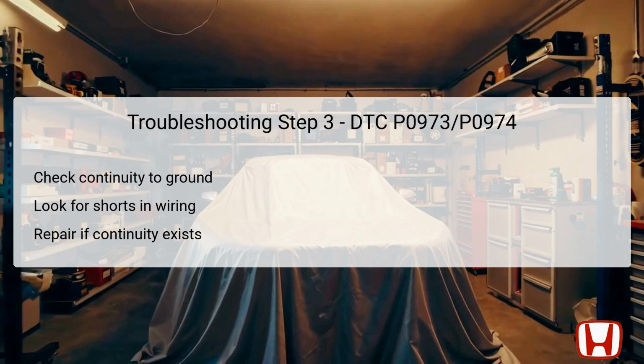The third troubleshooting step is to check for any shorted wires within the SHA and VBSOL circuits. This step involves checking continuity between specific terminals on the TCM 58P connector and the vehicle's body ground, while keeping the vehicle in the off or lock mode. Disconnect the TCM sub-harness 26P connector and the TCM 58P connector to prevent any interference during the testing.